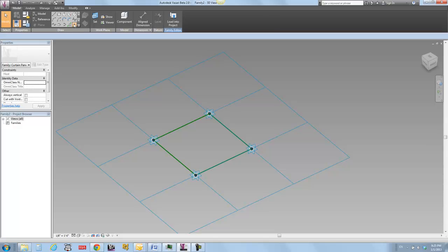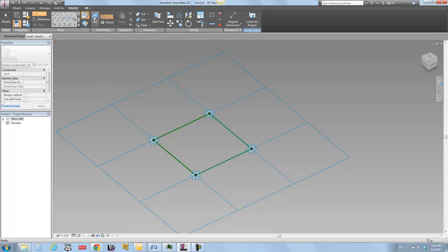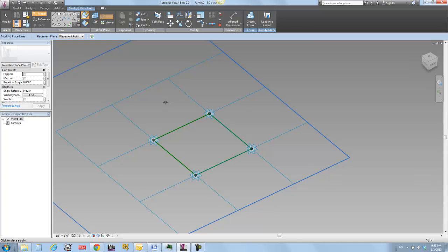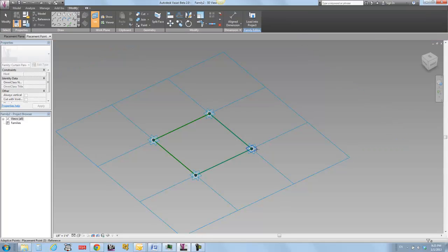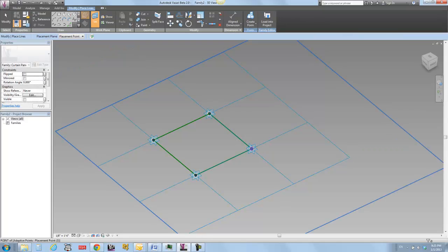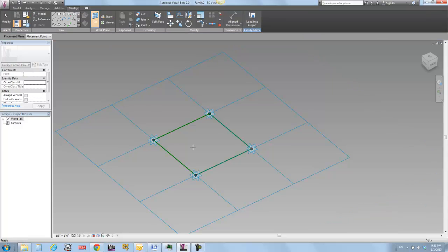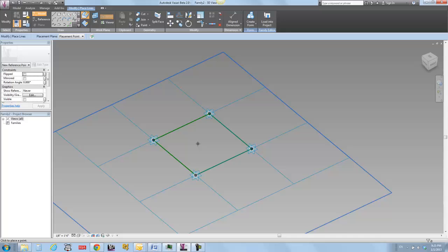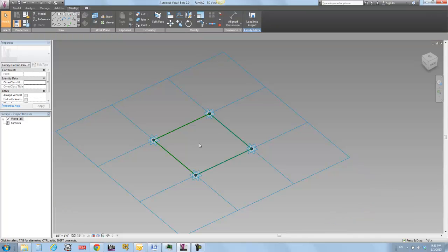If I activate my point tool and I make my set work plane tool, I'm going to set this work plane right here, the horizontal work plane at this point, to be active. And I'm going to plop a point right on top of it. And I'm going to do that 4 times. Set, point, set, point, set. Come on, keep up, ribbon. Point. So it looks like I've done absolutely nothing, right?